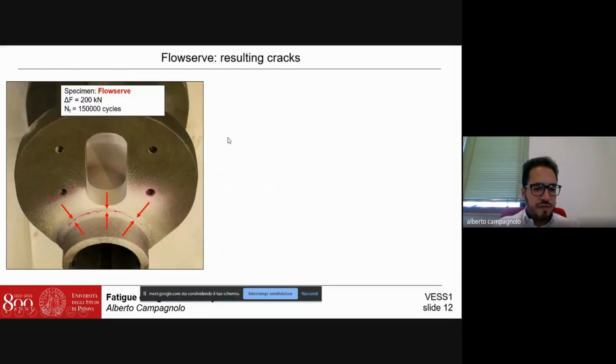Dealing with the Flowserve joint, we have observed that the cracks originate from the weld root side. Therefore, from this figure, we can see that the cracks did not initiate from the weld side between the yoke wing and the tube, but emerge almost in the middle of the weldment surface. As discussed previously, this is the typical cracking behavior of a crack originating from the weld root side.